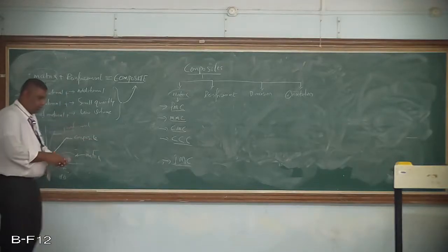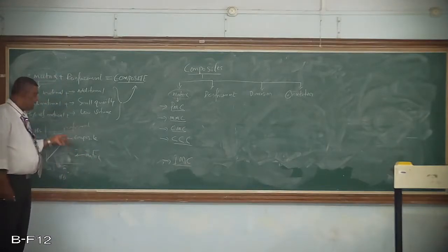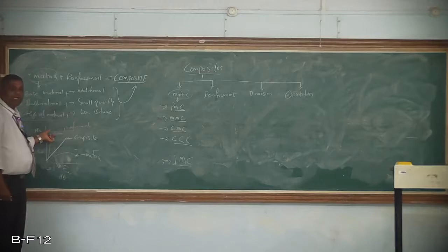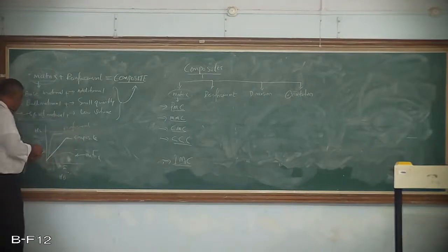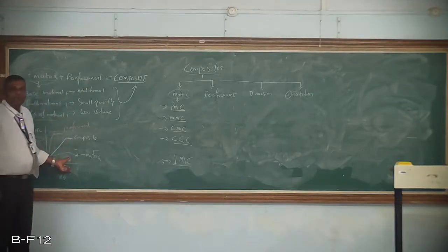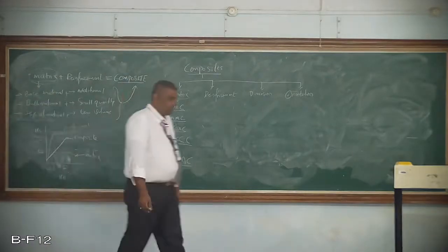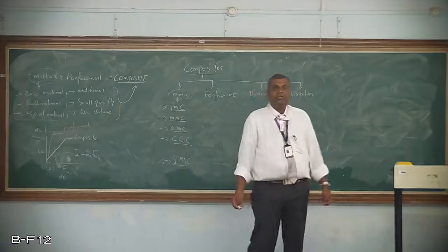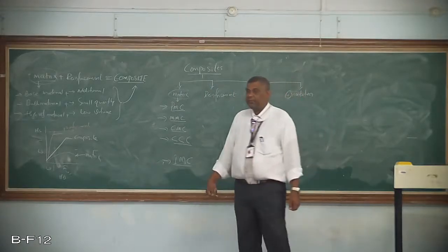So what I have done is combine the advantage of the matrix material and the advantage of the reinforced material, then it is called a composite material. Now I can see I have compensated a little bit of strength, but what I gained is more ductility. This type of requirement is called a tailor-made material. So generally a composite material is also called a tailor-made material.